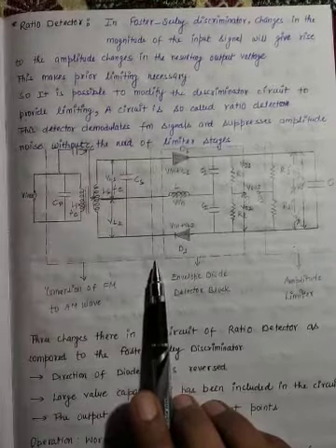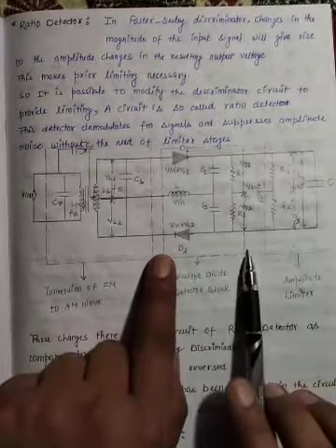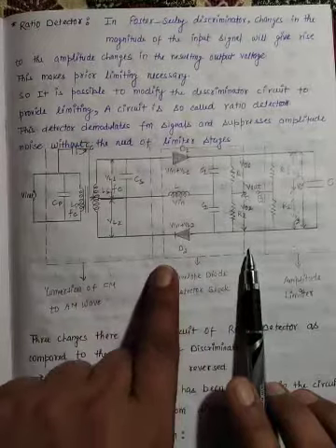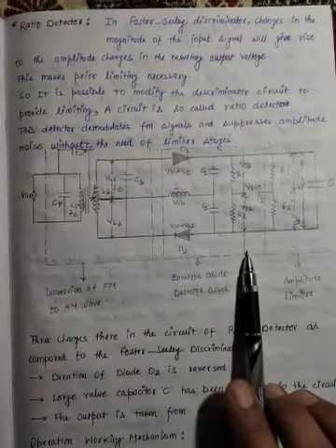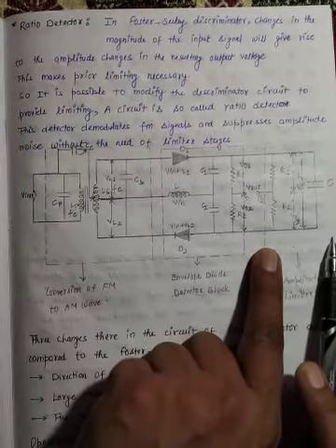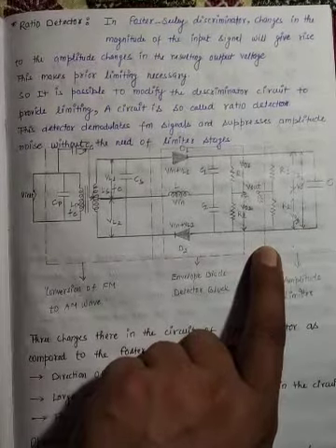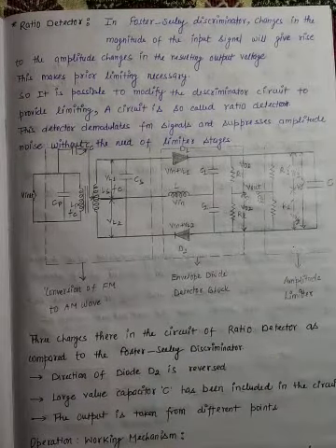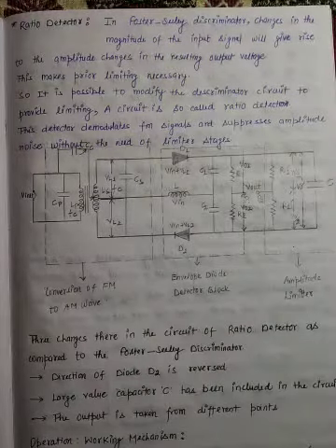This block converts this FM modulated wave into an amplitude modulated wave, and this wave, which has the amplitude modulated wave as input, extracts from there the modulating signal, and this modulating signal is given to this block, and this block maintains the amplitude of the modulating signal, or we can get a constant modulating signal which has constant amplitude. So these are three blocks which have different functions.